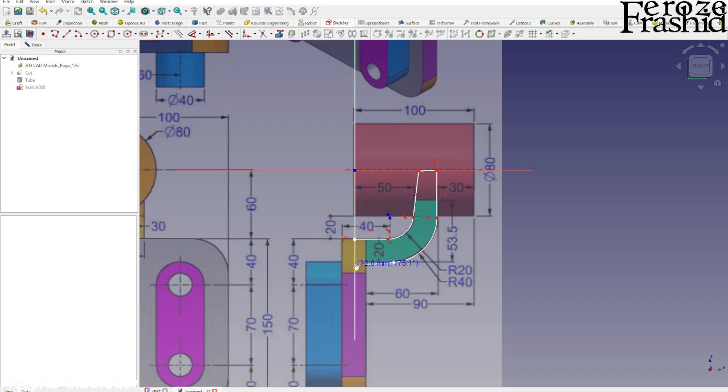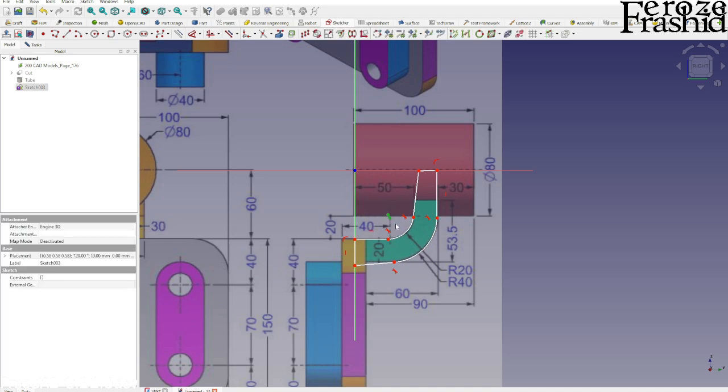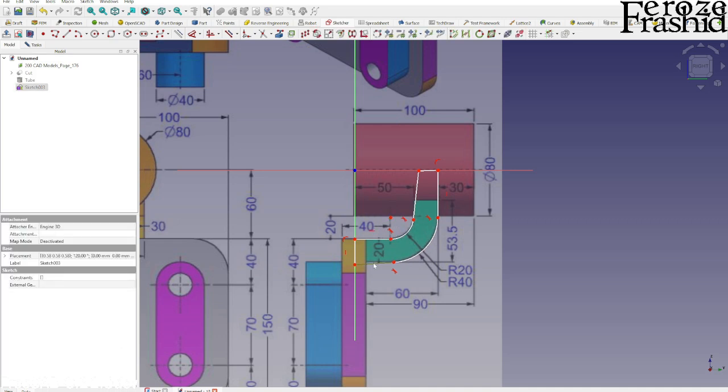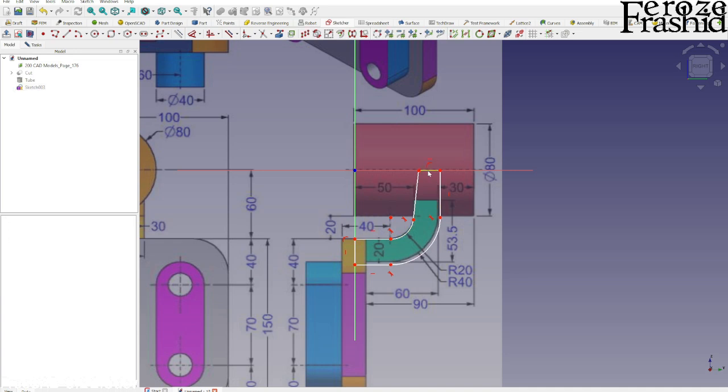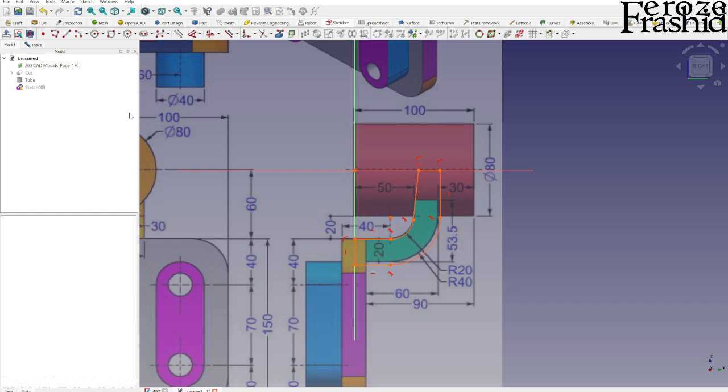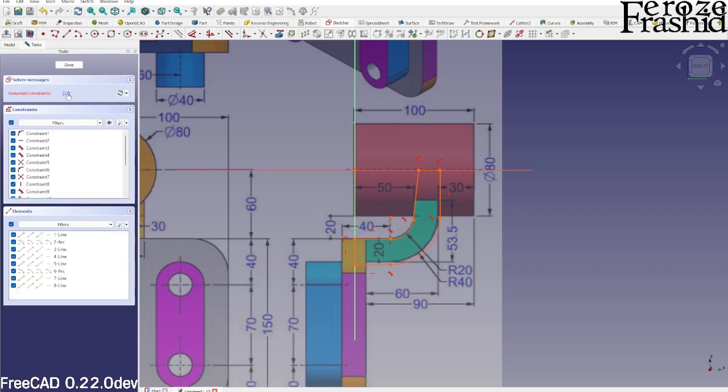All right, and come back to this axis and close it up. First of all, these two will be the same, so they're coincident. This would be horizontal, this would be horizontal, and this point will be on this axis. Oh, that's over constraint. Maybe it was there to begin with. And this will be vertical.